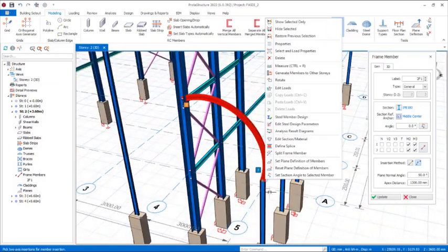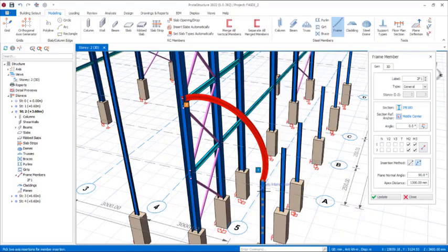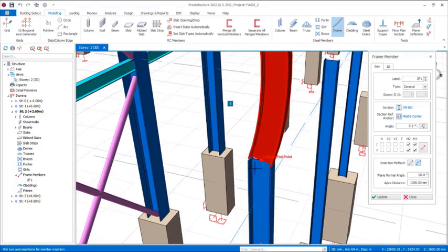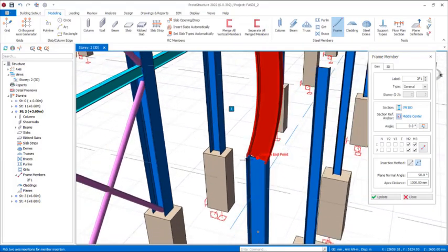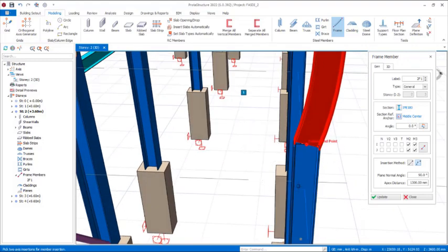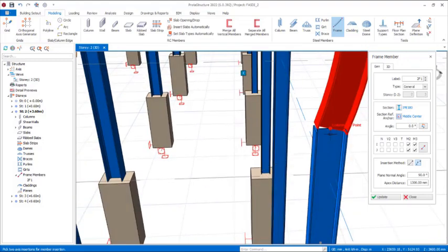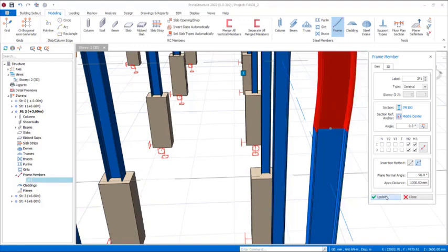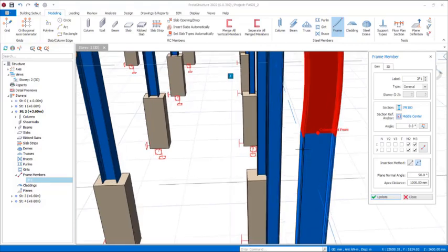You can see, but if you zoom closely now, you'll notice that this curved beam has not seated rightly on top of the vertical stanchion. So for you to make it sit right there, you need to come to these provisions, you can keep adjusting this. Let's say 1000. If you keep 1000 millimeters right here now, click on the update, you can see it has sat right there. So this is what I actually expected.